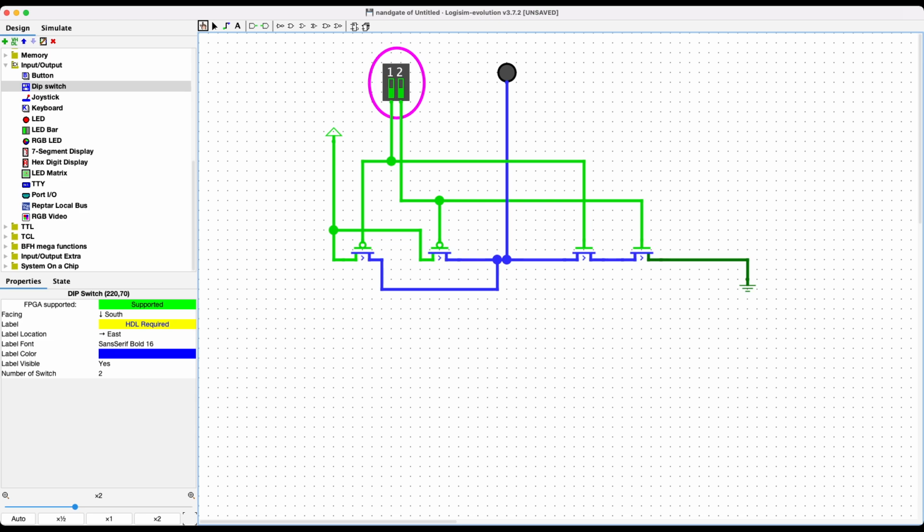So anyway, okay. So I've wired my two NMOSs here in series. How have I wired the PMOSs? And I know it's a little bit of a rat's nest, but kind of stare at them for a minute. And the way you sort of answer this is how could you get from the voltage source, which is just underneath my mouse cursor, to the right side of either of the two PMOS transistors? I could theoretically go through either one independently. I don't have to go through both, right? That means they're wired in parallel.